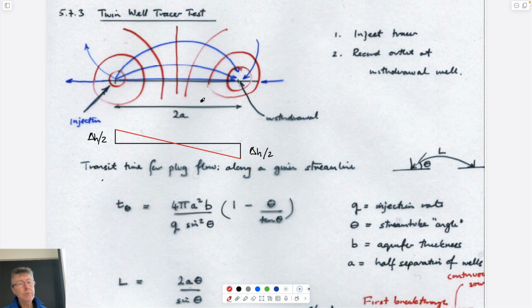And so the point is that this would be the flow line as you go between this point and this point. The streamline between this one is much longer, has to be the same gradient, and so by definition, has to be the same drop. The drop between upstream and downstream is the same. It flows much longer, so the gradient has to be smaller, and so the velocity has to be smaller as well.